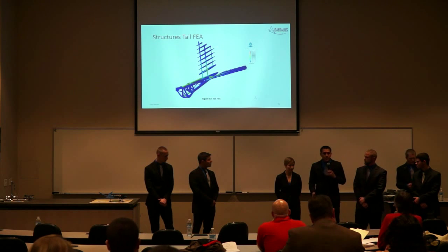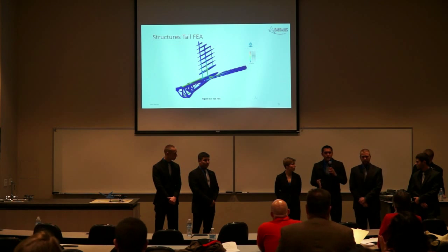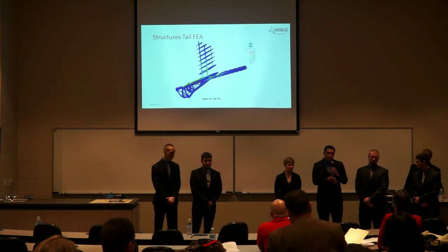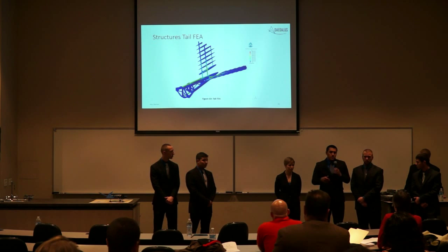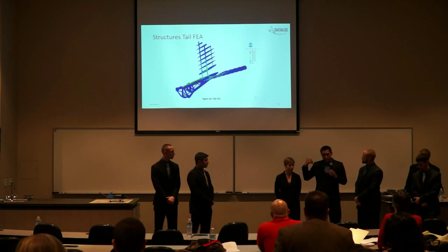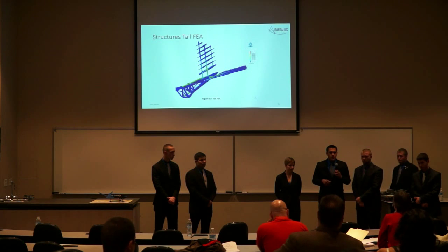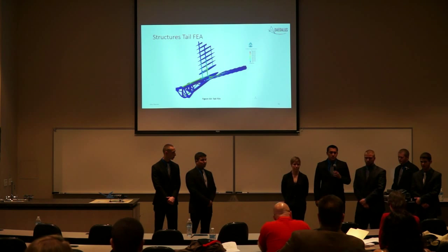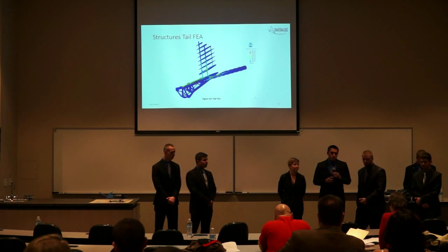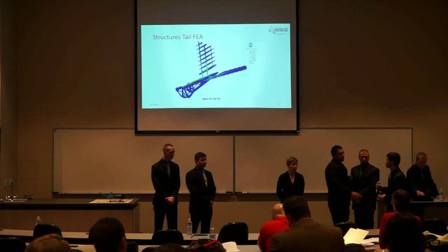Yeah, so in the event of an engine-out scenario, due to the fact that the engines are so close to the midline of the aircraft, one single engine isn't causing that much of a moment. So due to the size of the V-tail, it could easily correct it. Okay, within that 1.5 safety factor. Yes, ma'am. Definitely. And then the last question is, looking at your constraint diagram, you have a takeoff requirement at Mach 0.22.